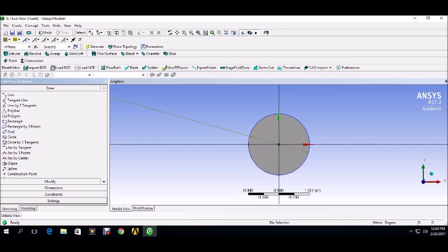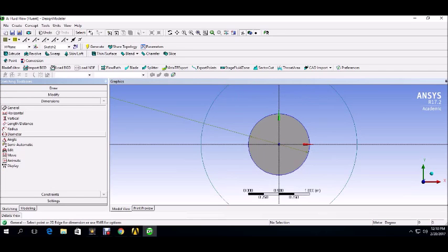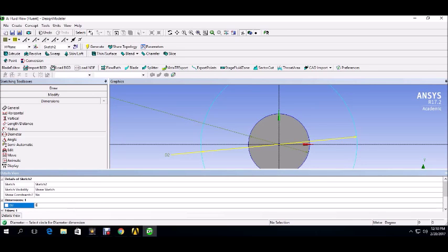Okay, now we're making the outer circle. The importance of it is that you have to make it large enough so that we're still getting all the fluid flow that's acting on the inner cylinder, but we're not affecting any of the flow that's acting on the inner cylinder. So we have to make the outer circle large. We're going to make sure we're at 0, 0 again. Just make a circle. We're going to give it dimensions. We're going to make this a lot bigger than the other circle so it doesn't affect any of the flow. Details, we're going to make this 64 meters in diameter.